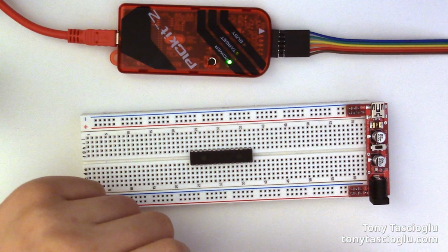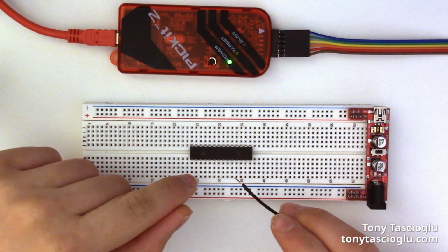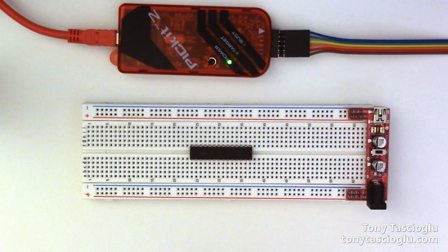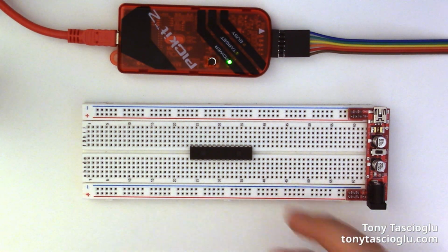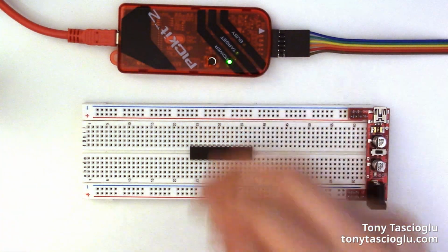When the PICkit is connected, it actually doesn't activate at first. The PICkit will only power this chip and set the appropriate pins when you're actually uploading a program. This means that during idle time, you still need to power, like if you want to run your program, you will need to provide separate power to the chip. It will not receive it.